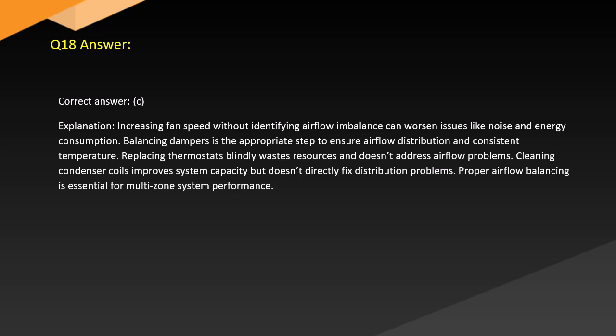Replacing thermostats blindly wastes resources and doesn't address airflow problems. Cleaning condenser coils improves system capacity but doesn't directly fix distribution problems. Proper airflow balance is essential for multi-zone system performance.